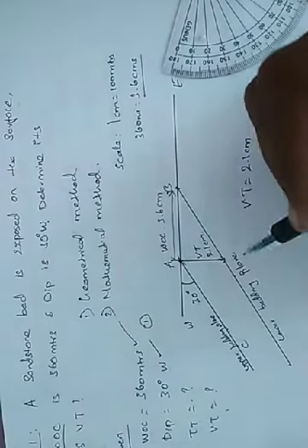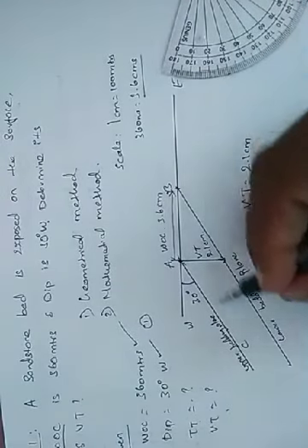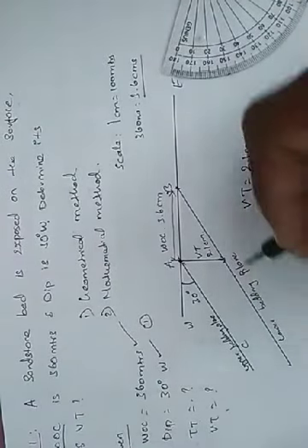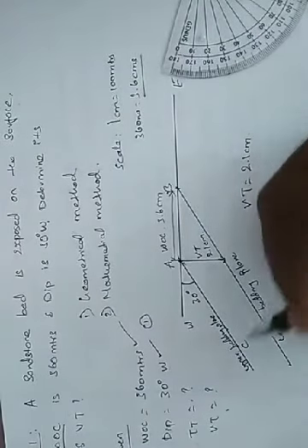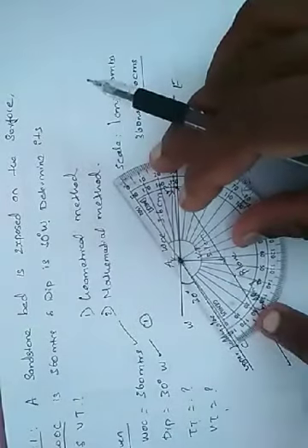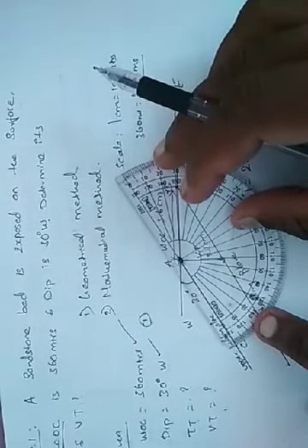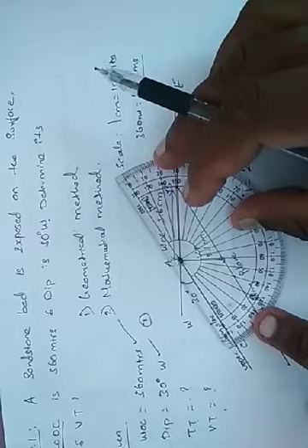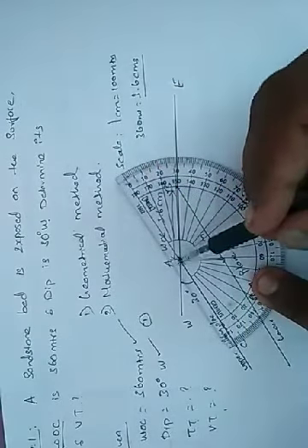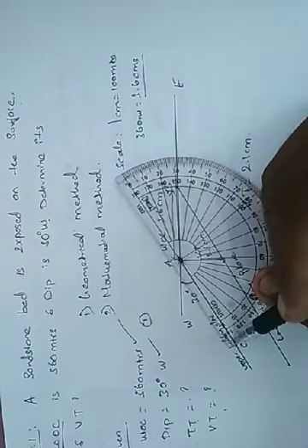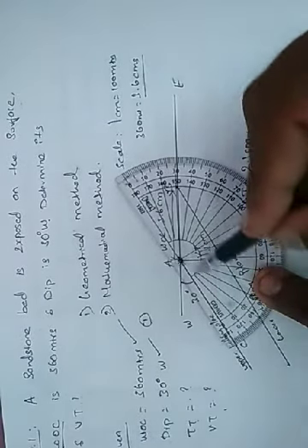So these are the two bedding planes what we have. So we can mark any point on these lines and we can draw one perpendicular line that gives us the true thickness. So I will take from the point A itself. To get the perpendicular line, I will use the protractor and place it on the point A, coinciding the 0 with the upper bedding plane the same way.